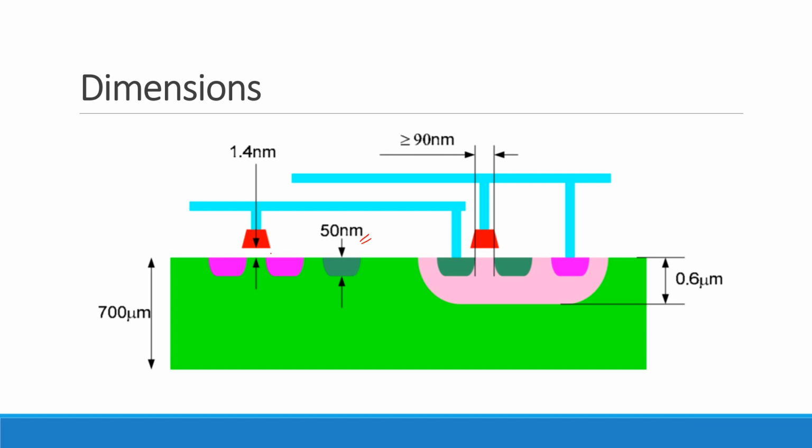Anytime you've got stuff that's thin, if you go for any appreciable distance, there's going to be resistance there, right? So just like you said, every time you draw one of these transistors, there's actually some fairly substantial series resistance in those source drain regions. In fact, if you look at scaling, that's one of the big deals in terms of things that people worry about, how they're going to take care of that. Okay, so another thing to keep in mind.